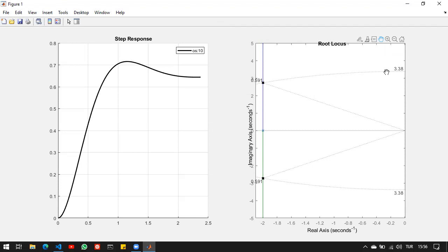Of course, the omega n value will change, because if you increase zeta a little bit, then the omega n value should be decreased, because the multiplication here is constant, because it gives me the real value, and the real coordinate of all the possible solutions with a P-type controller will be on this exact line with the same real value.